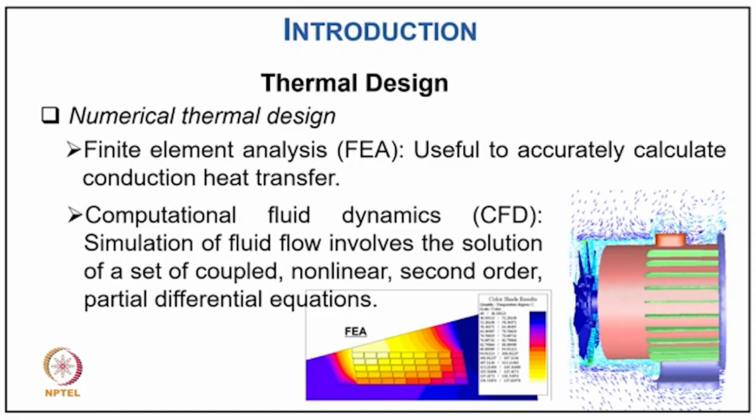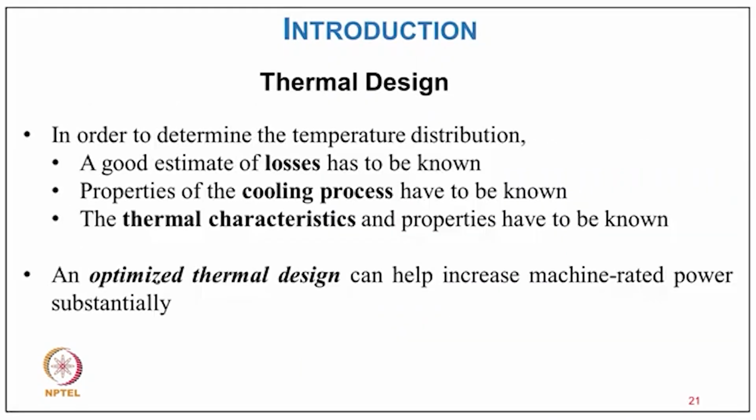Now coming to numerical thermal design: the first approach is finite element analysis, used to accurately calculate conduction heat transfer, as you can see in the diagram of finite element analysis and computational fluid dynamics. The simulation of fluid flow involves the solution of coupled nonlinear second-order partial differential equations. Nowadays, of course, we also have thermal scanners for these machines to get the actual temperature distribution, or a thermal image of the actual machine. So in light of that, we have to go into more detailed calculation.